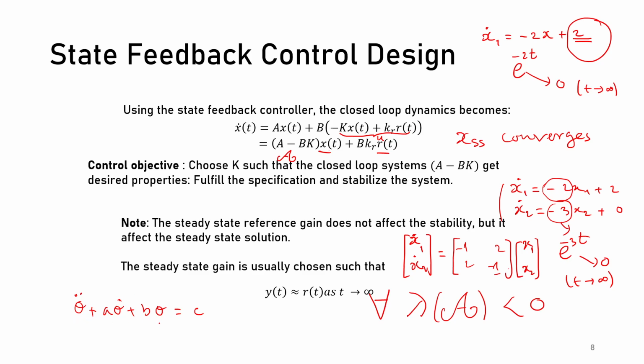If we use the characteristic equation, or the transfer function, what is the condition for the system to be stable? If you use the transfer function, you remember the poles? All the poles have to be on the left-hand side of the complex plane. Or we can say the real parts of all the poles need to be negative.